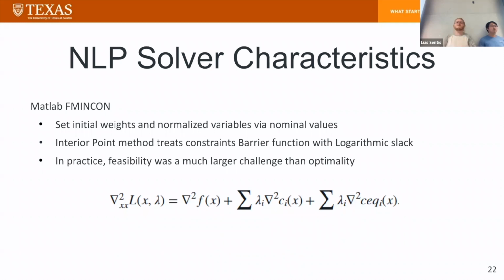Normalizing the variables is also important. If you remember Bryson's rule from LQR, we basically did that, where you say a joint angle should not be more than like 0.1 radians or something, and you can smooth those out a little bit.